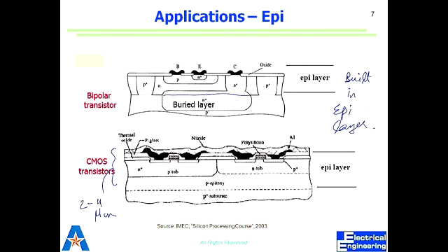So you need carriers, but you don't need too high of resistivity in the channel region. Will the resistivity always go down as you dope it? Resistivity goes down, but then it goes up because too much doping results in less mobility. Why?